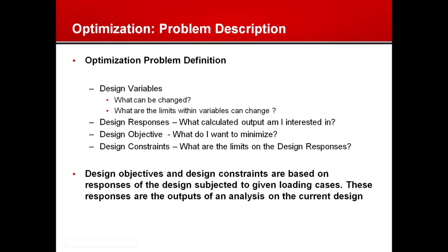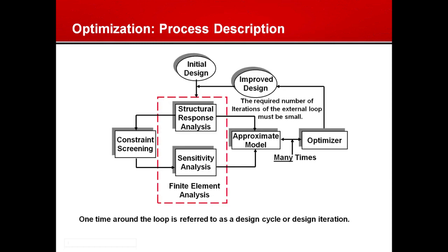And that's always multidisciplinary. So you can have a static constraint as well as modal buckling or frequency response type of constraint in the same run.